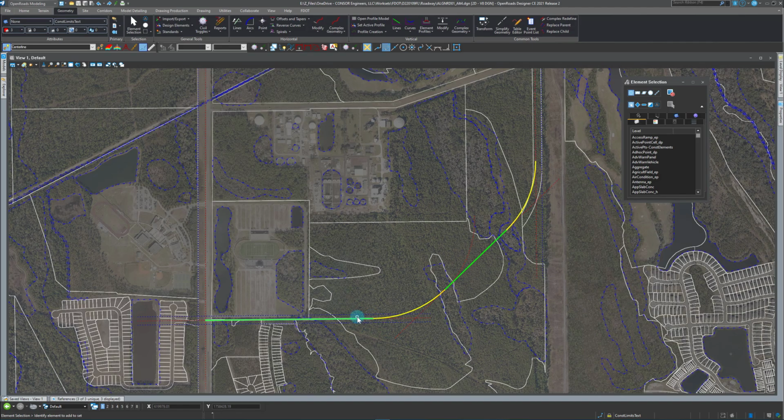So let's just say eventually I wanted to look at moving this alignment up to this area here and using this right away. One of the things you want to do first is click this arc, because right now as I drew it, it hasn't locked its distance. It's basically going to hold this point in space right now.